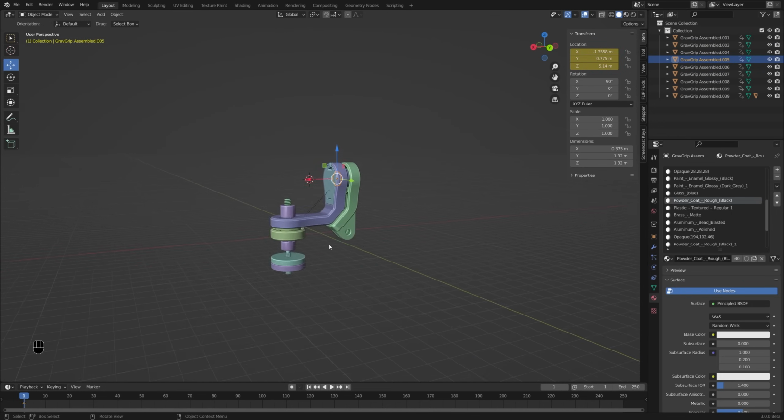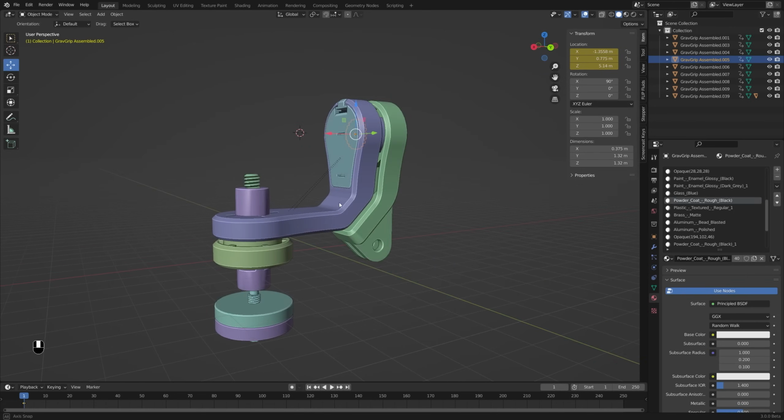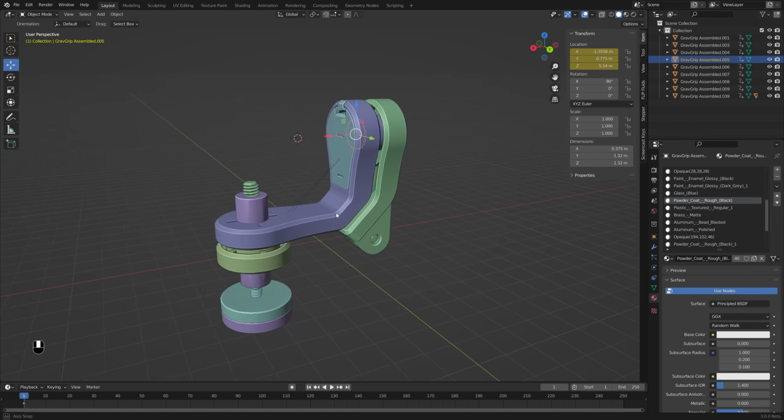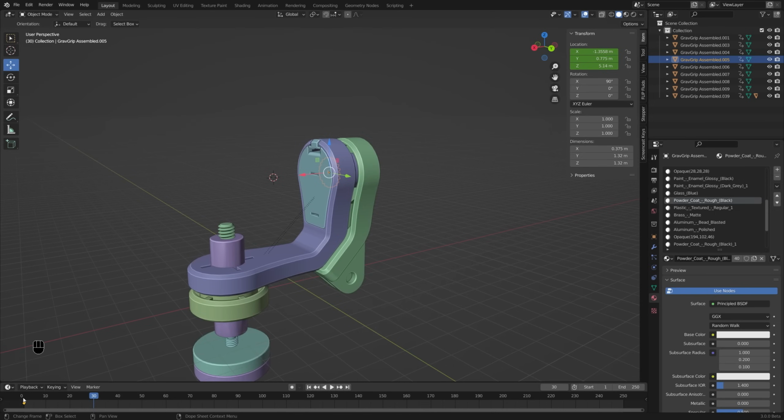And that's one thing that's really great about keyframes too, besides just using them for animation, obviously, is you can use them as like save states to make sure things stay in place. I do that sometimes when I'm doing still renders, I'll actually add animation to the objects just to hold them in different positions. But what I'm going to do now is just advance to a known frame.